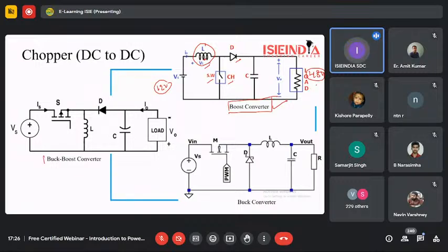And now when we talk about the buck boost converter, depending upon the switching frequency and duty ratio, this converter mainly acts as bidirectional. The output voltage sometimes becomes higher as compared to the input, and sometimes the input voltage becomes higher as compared to the output voltage. So it totally depends upon the duty ratio, D. Duty ratio is basically T on divided by T total.